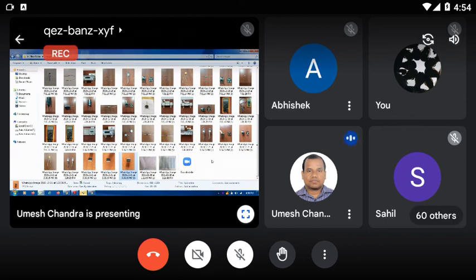That inductor you cannot measure in a simple multimeter. That meter is known as LCR meter. Actually, in the LCR meter, you measure the exact capacitance value. But in this multimeter, if you measure the capacitance value, you will not get the exact value. But if you measure the capacitance value in LCR meter, then you get the exact value. LCR, L means inductor, C means capacitor, R means resistor.